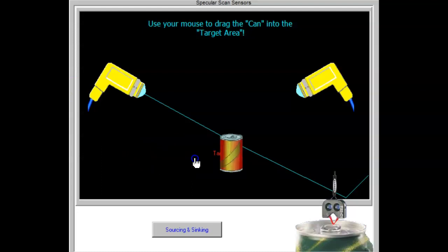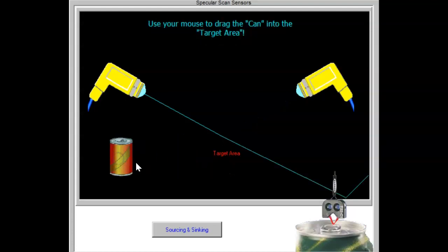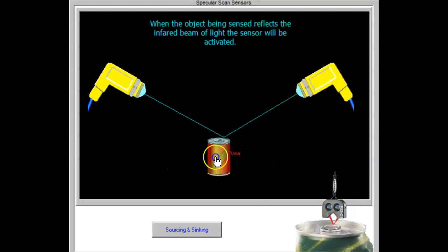Positioning of both the light source and the photoreceiver are critical. The distance from the source to the surface and the distance from the surface to the receiver must also be consistently controlled. If they are not, the light will be lost due to improper angle. The size of the angle determines the depth of the scanning field. This makes this type of scanning an excellent choice for use in fill detection, such as controlling the level of a liquid in a vessel.